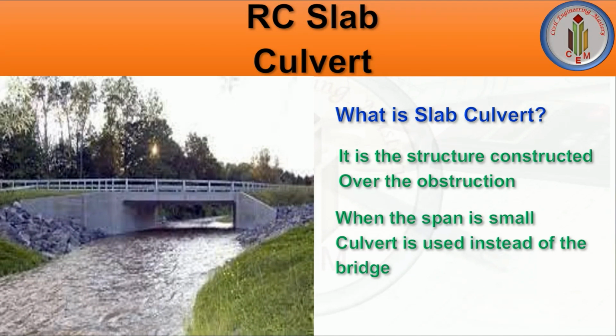These kinds of culverts are commonly used both as cross drains for channel release and to pass water under a road at natural drainage and river crossings. Culverts can be built with different materials such as masonry, concrete, bricks, stone, or reinforced cement concrete. Slab culverts do not have a bottom slab, therefore the natural flow of water is maintained and the natural bottom substrate remains intact. While constructing these slab culverts, a series of slabs are laid to form a bridge-like structure. After that, a pavement surface is placed on top to serve as a road.